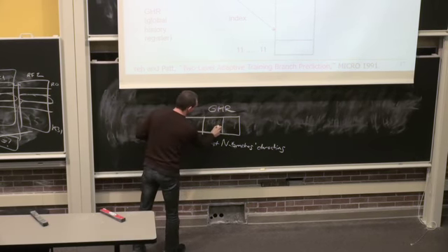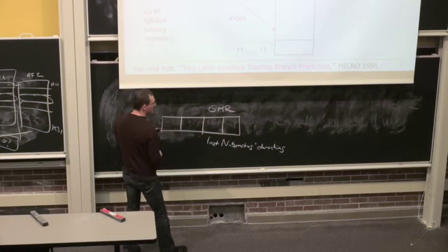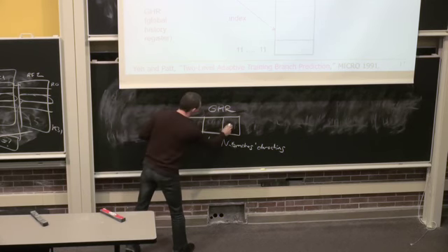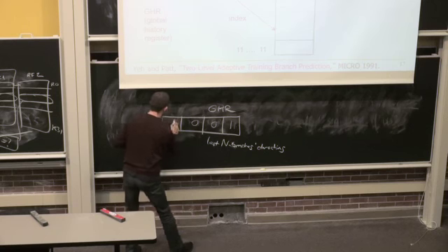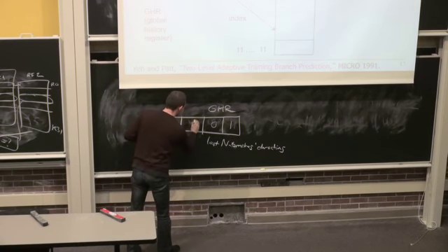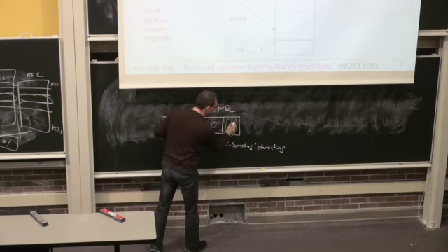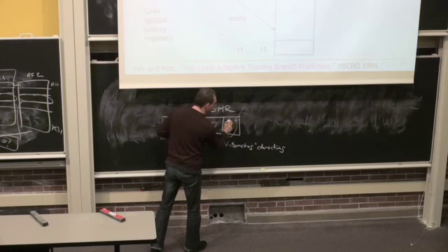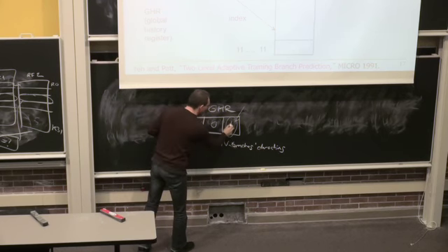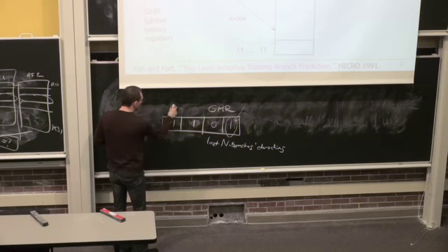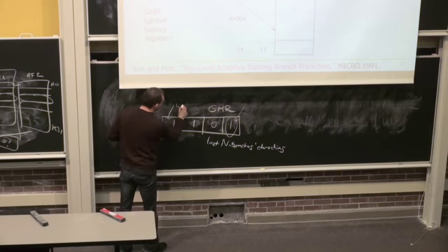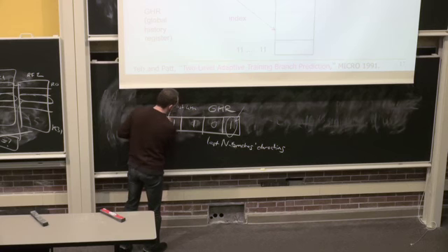You can keep track of the direction the last 4 branches went. It could be 1, 0, 0, 1. Well, let's make it a little bit asymmetric: 1, 1, 0, 1. This could be the last branch. Where did the last branch that's executed go? 1 could be taken, 0 could be not taken. Where did the previous 4th branch go?